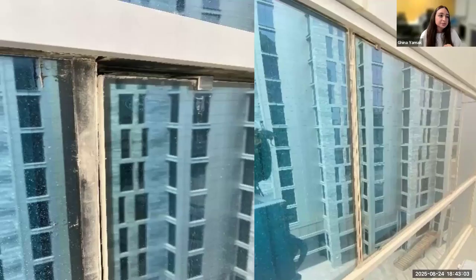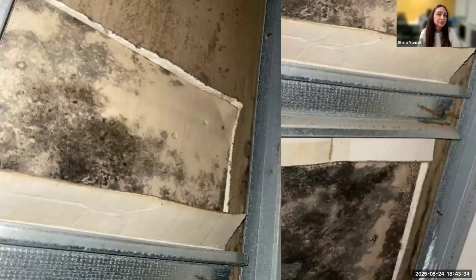For example, on those pictures, we can see that the window is not aligned at all with the curtain wall, and the frame is just not there. I mean, it can be frameless, yes, but it's just misaligned and it doesn't close properly with the curtain wall. This will lead us to water leakage for sure, and to air ingress for sure, which will lead eventually as well to what? To humidity, fungus, very bad conditions that can happen on the interior finishing and fit out.